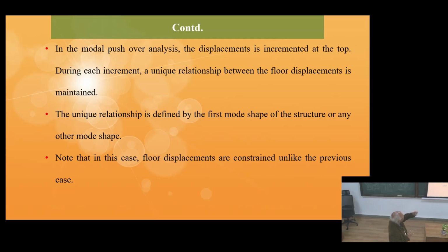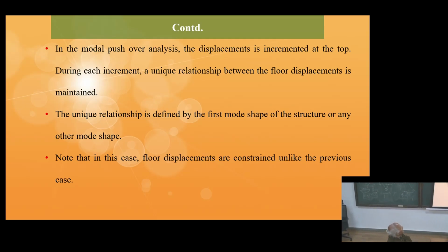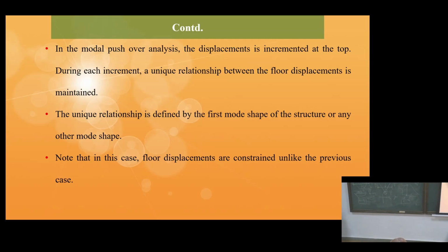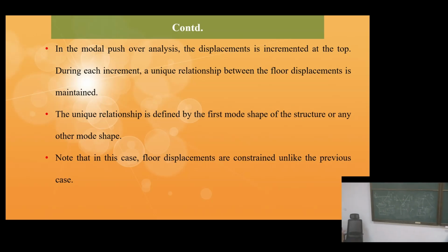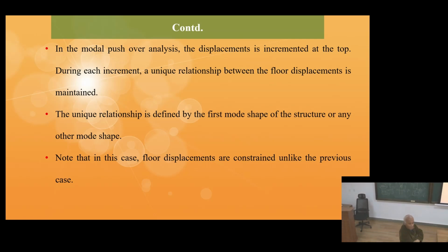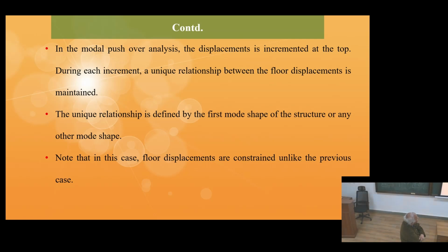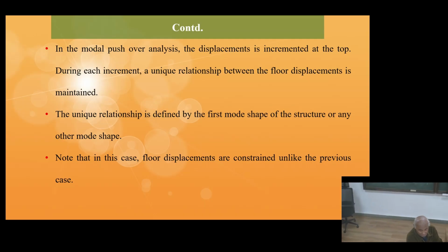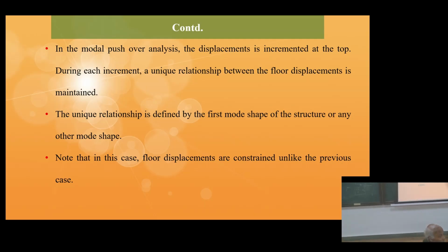This mode shape is given. So now what I am trying to say is that in the modal pushover analysis, the displacement is incremented at the top. At the top I am giving. During each increment, a unique relationship between the floor displacements is maintained. That means I am putting a constraint now.